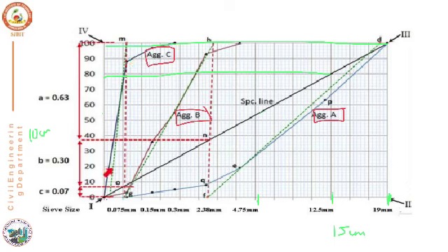So after drawing the gradation line, we have to draw the balancing line, which are the dotted lines. When you draw the balancing line, ensure that the area above the balancing line and the area below the balancing line will be equal. So I mean to say that if you consider here, this will be the area above the balancing line, and this is the area below the balancing line. You have to draw an average line such that these two areas will be approximately equal. Similarly, draw the balancing line for aggregate B and aggregate C.